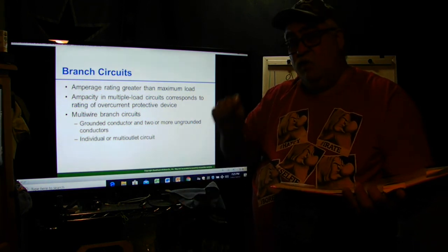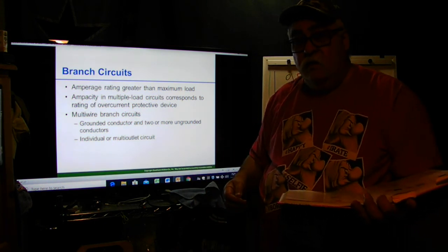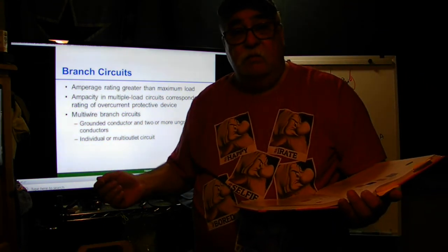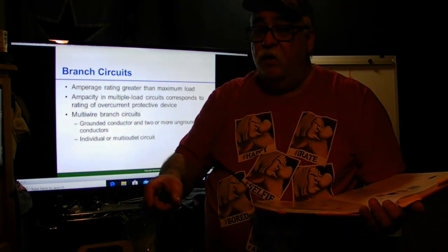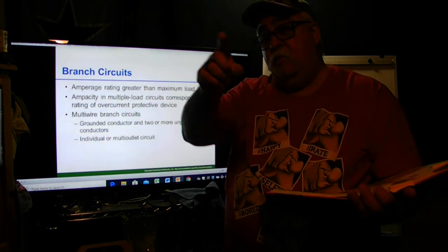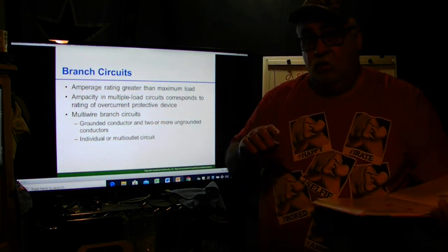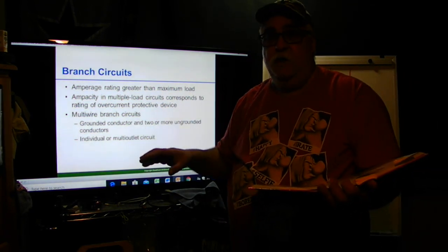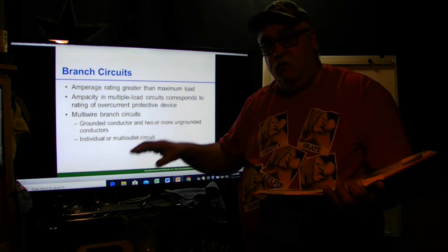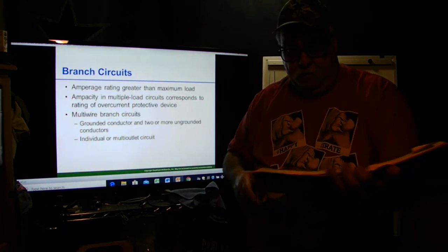So I can have that, as long as the wire can carry the loads that are being plugged in. Same thing with a water heater. The water heater may say 22 amps. Well, I can't put a 25 on it, so I got to put a 30, the next size up. But the wire's got to be able to handle the load that's being plugged in. So the ampacity of the wire has to match the ampacity of the equipment. The breaker may be a step up.